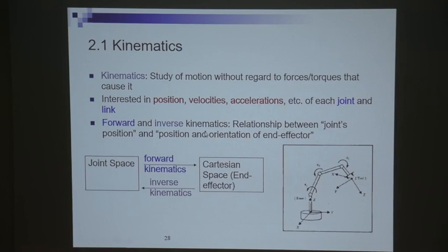The inverse kinematics is a lot harder. When you turn the joint angles, being rigidly attached, you multiply a series of matrices and then you get the end effector position. But when you're given a position and you try to calculate backward, you may find that it's not so straightforward. In some cases, you may have no solutions. You can't reach that point. In some cases, you have multiple solutions, and multiple solutions may not necessarily be a good thing.